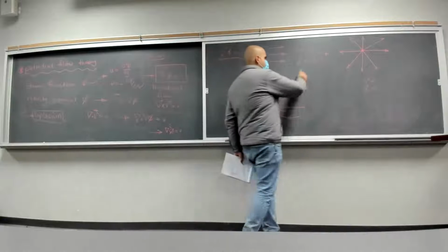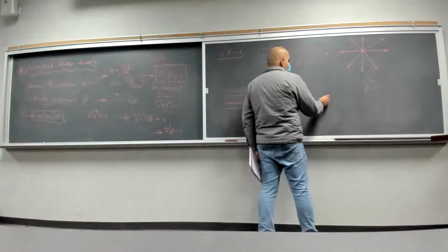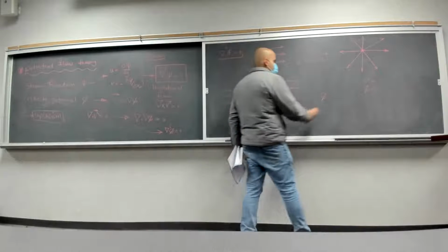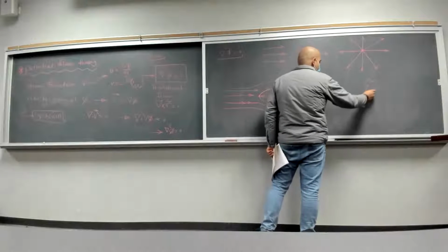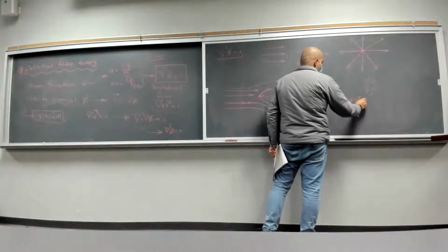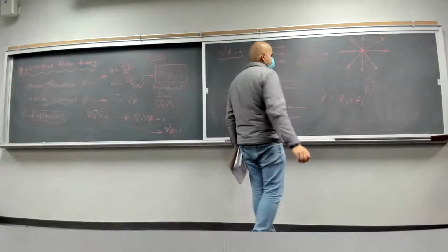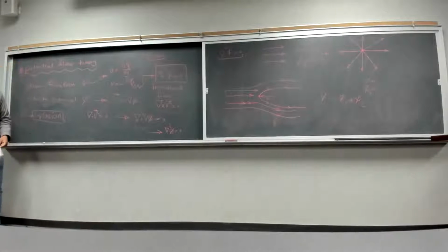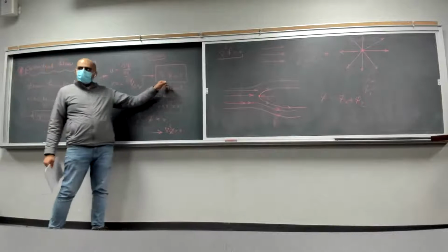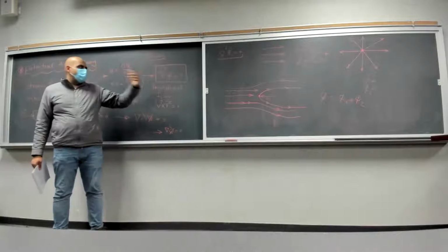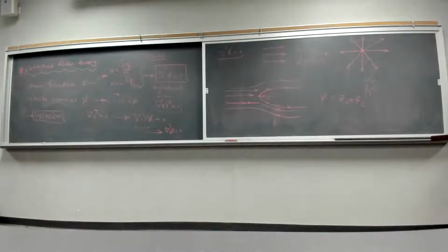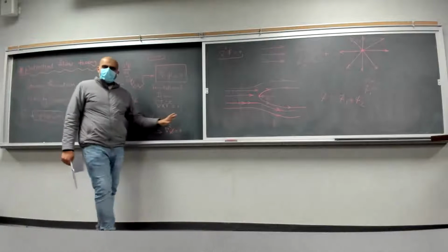And if you have the velocity potential for these two, we're going to find the velocity potential for this more complex flow by just adding them. Velocity potential of this, phi 1, plus the velocity potential of this. Yes? And the reason that we can add them together is because the Laplacian of both of them is equal to 0. Yes, that's one of the main characteristics of this type of function. Harmonic functions, yeah. Exactly. Did it become a little more clear?